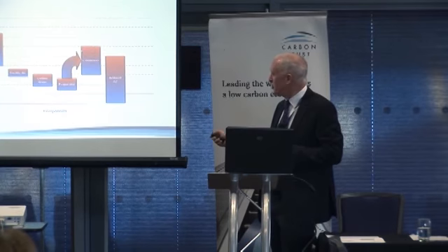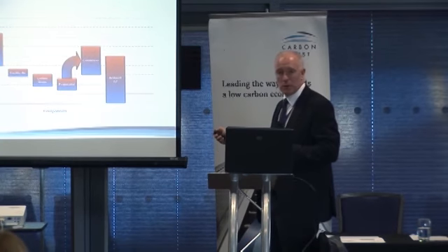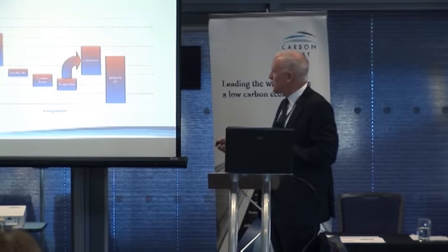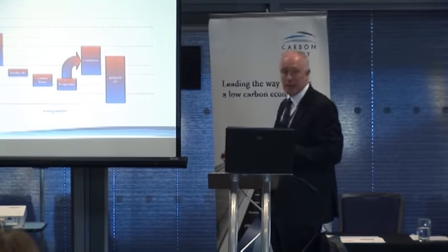Why we're doing all this refrigeration is quite surprising when the outside air can do it. So we need to question that. So that's a big area to look at. And the other area to look at is, if we are doing chilling, then there's a lot of waste heat here. And this sort of temperature of waste heat can be very, very useful.